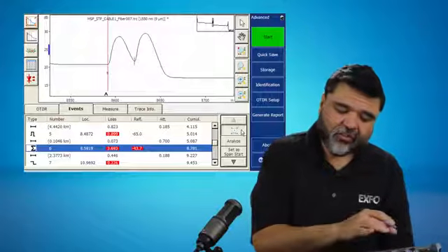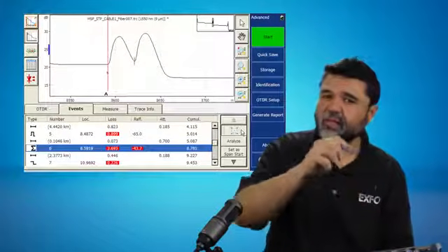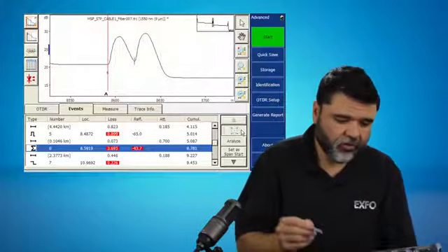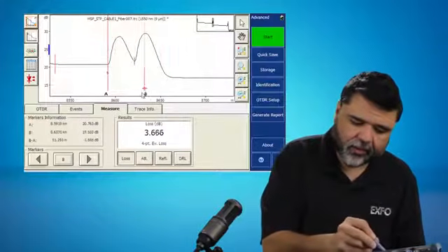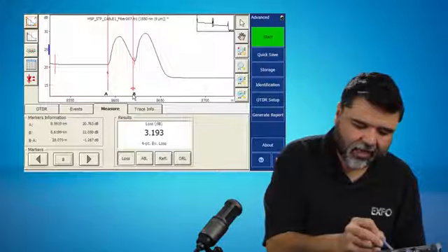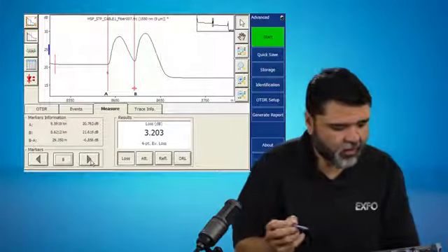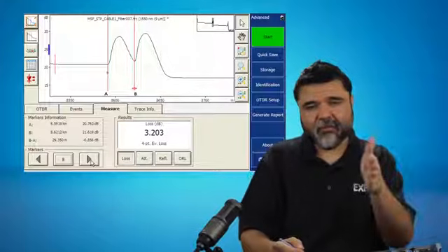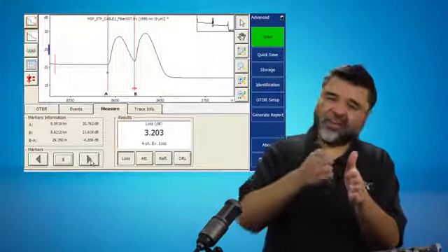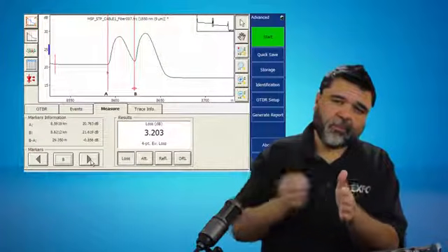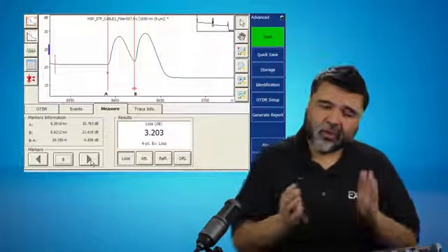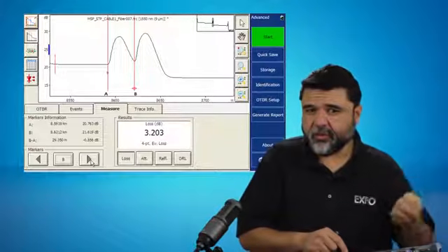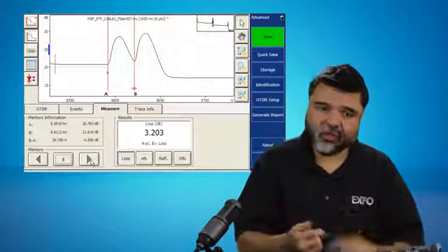So you can see the two humps there, the two reflective humps. So we identify that there's probably two connectors there close to each other. If I turn on the measurement tab and then move my marker over, I have a connector about 29 meters apart. So after that first connection, there's another connector about 29 meters away. The problem is that there might be a lot going on there, so I don't know if all my loss from this particular location is coming from the first connector, the second connector, or something in between.